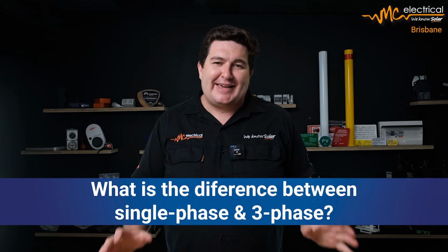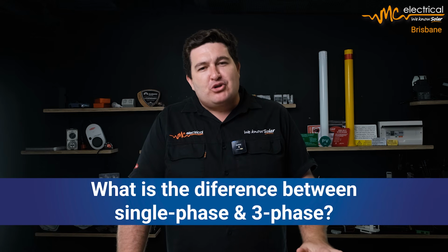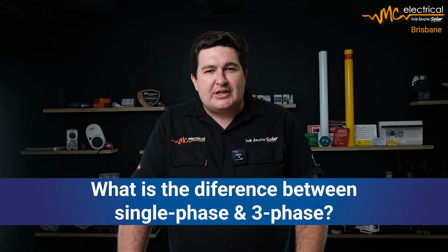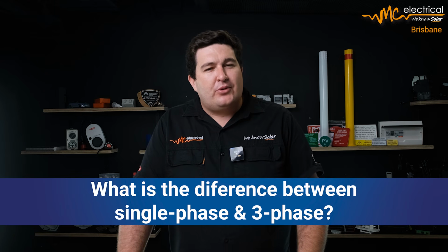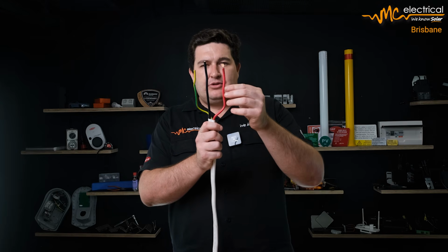So regardless of if you're going to get a string inverter or a microinverter, a hybrid or a non-hybrid, one of the most common questions you'll get asked when you start looking at solar is, do you have single phase or three phase to your house? Now, most homes in Australia, especially if they're a smaller home, will be a single phase connection. And the best way to think about single phase is it's one AC wave coming in, whereas with three phase, you'll have three AC waves coming in. And there's a few ways you can tell if you've got single phase or three phase. But from the really simple standpoint, when we've got a connection to the grid, we've got three cables.